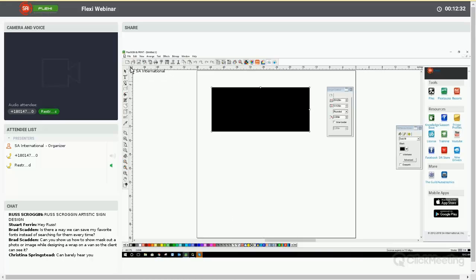We can always double click on this little icon and it will open ruler and grid settings. If we need to change our orientation of the page, X and Y, we can change it with the buttons here, or you can specify where our X and Y are. Because our orientation is set to be lower left origin, I can always go back to it by typing 0 and 0 over here. And you can see where the 0 is now on the bottom and on the top here on the left.